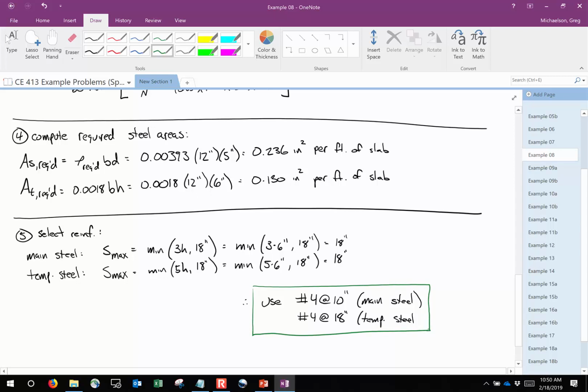Well, it's usually spec'd out in the drawings. That's a fair question, and the short answer, if we're talking about structural changes, is that the contractor needs to reflect those structural changes to the engineer. And if not, then that's how you get Hyatt Regency, what we talked about in steel design. So yeah. Now, I say that this is the answer, and spoiler alert, it is, but there's one thing that we forgot. Phi should be verified.